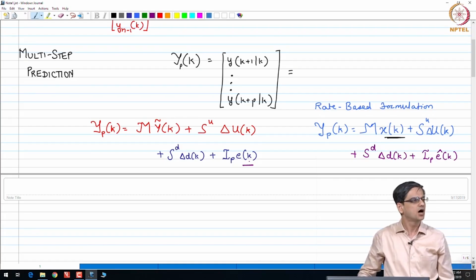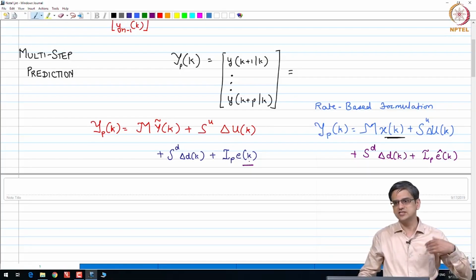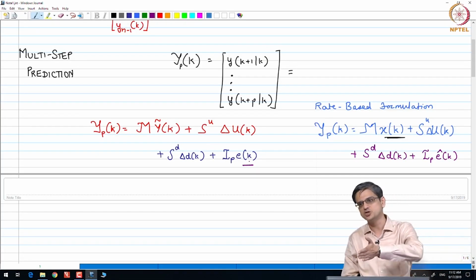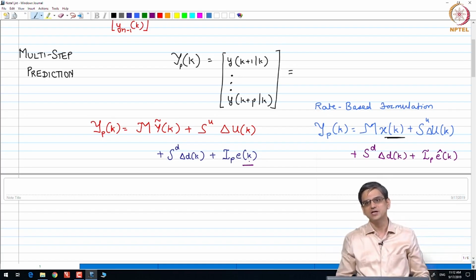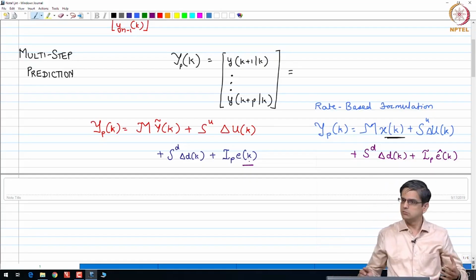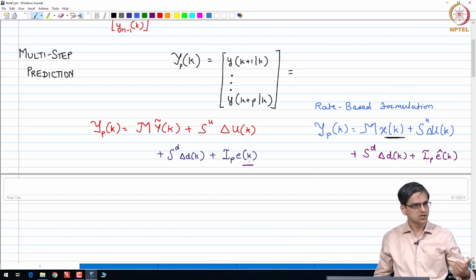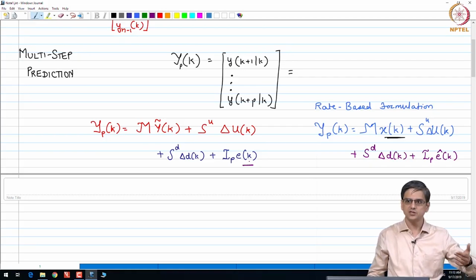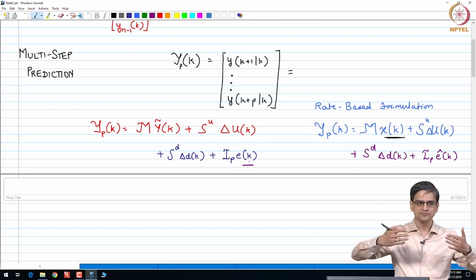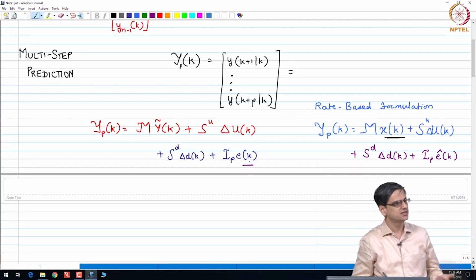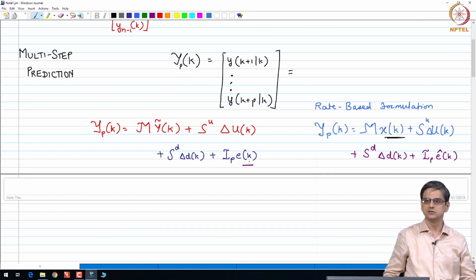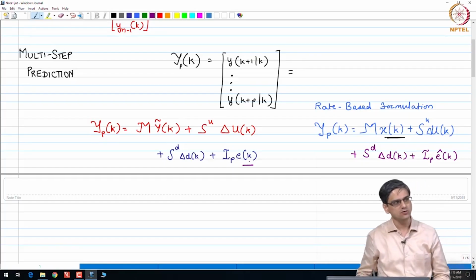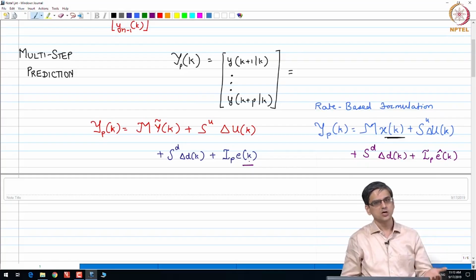Now, why are those two things a little bit different? They are a little bit different just because of the structure of your state. In case of a step response matrix, the state is nothing but predictions of future output. So, all you need to do is move all the future outputs by a certain amount. But let us think about a reactor. Your states might be concentration of A, concentration of B, temperature of the jacket, but your controlled variable might just be concentration of A and nothing else. So, based on concentration of A, you can't just arbitrarily move everything by the same amount. If the error in concentration of A is 0.1, it does not mean that the error in temperature would be 0.1 also. So, it is not immediately known how you are going to move those values. So, how to do that?